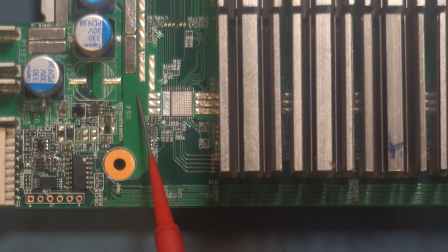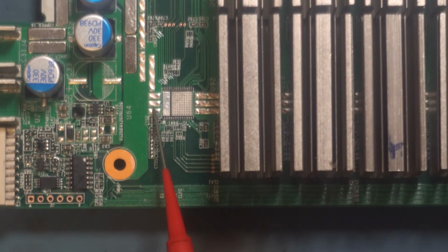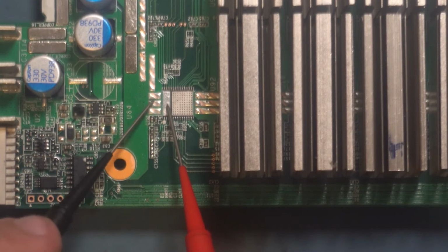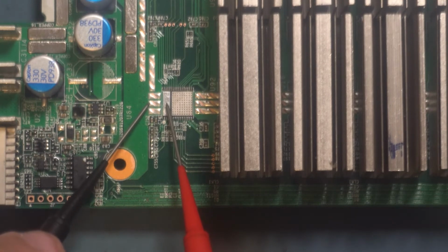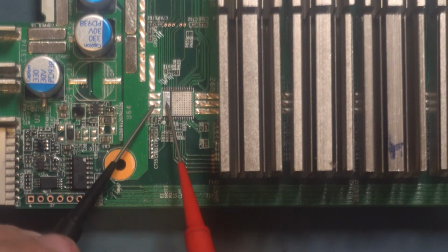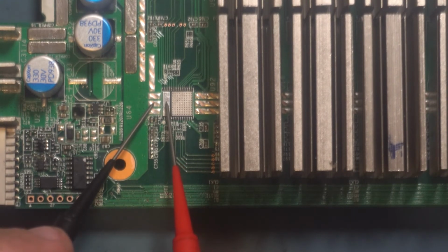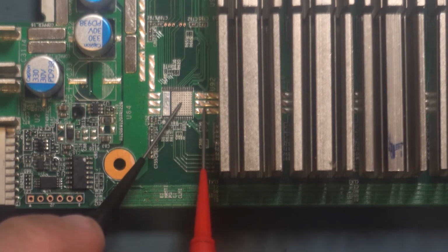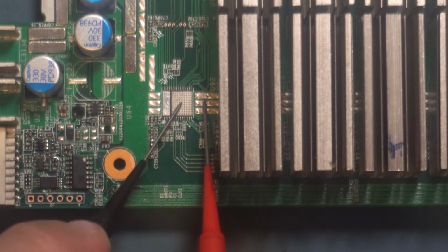And so you see again this big copper piece, which is the most positive supply, and this is where our traces begin. This positive pad is directly connected to these traces. I don't have my multimeter on right now, but trust me 100% that this is a complete short. This is all connected together. And the same thing between this main negative pad and the traces on this side. So this is again directly connected.